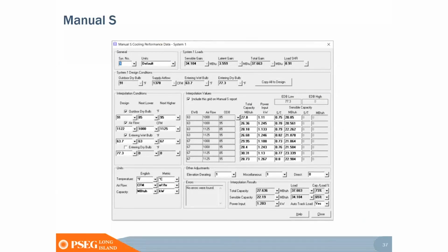The last thing that comes with the Manual J software package is Manual S, and this is regarding the expanded system performance data. So the Manual S will tell you your system size, if it's too small or too large, depending on data that's outside the normal AHRI range. So AHRI is at 95 degrees cooling, but it's not always 95. Like our Manual J at LaGuardia was 90, 91. So the Manual S will help you determine make sure you're not oversized on the sensible and the latent side with your equipment selection.